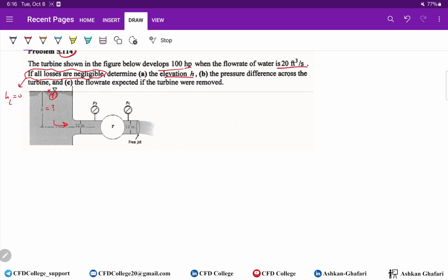But what do we know about these? It's only the outlet that we know something about, the pressure at least. We don't know the pressure at point 3 or point 4, but we know the pressure at the outlet, point 2, because it's atmosphere. We don't know velocity in any of these points, but at least at P2 we know the pressure, so it might be helpful.